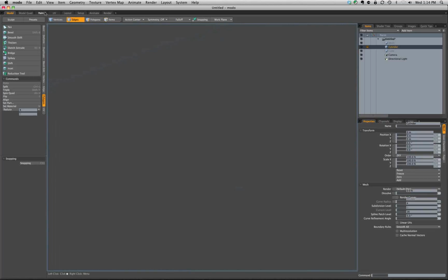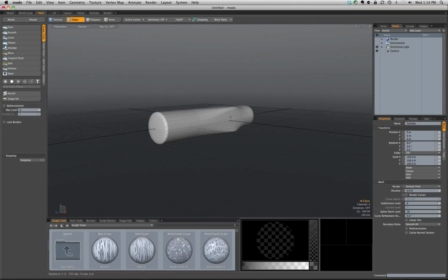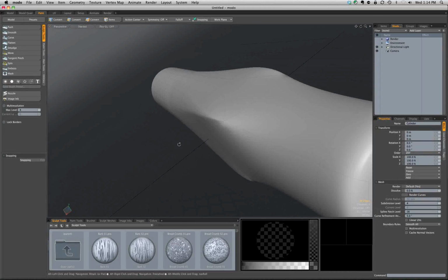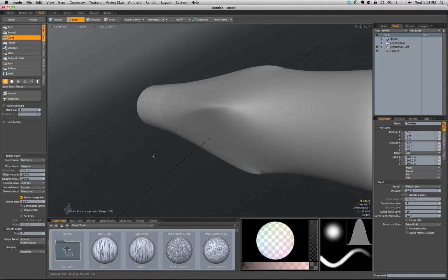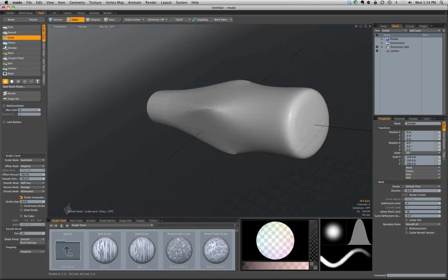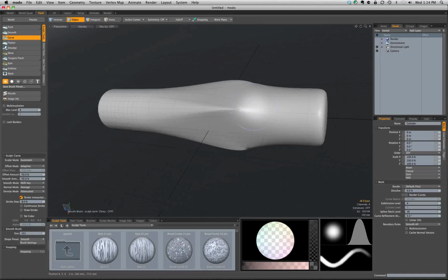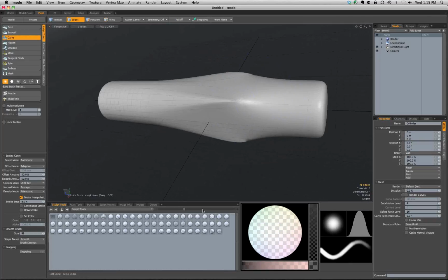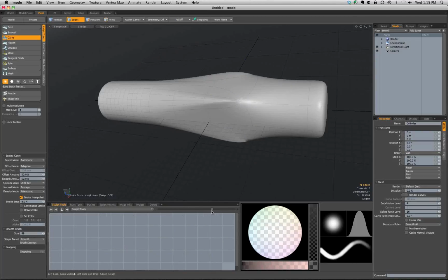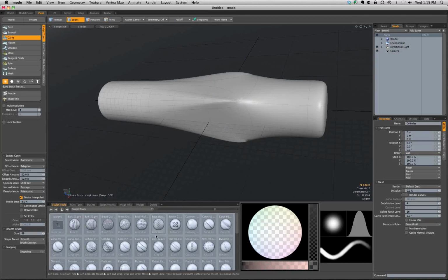So if I go over to the Paint tab and we take a look at our object and go under the Sculpt Tools, and we can just do something like Carve, notice that the tip also gets automatically selected. That's something new for 501 because it is all about workflow. So with the right mouse, I can increase that, and if you take a look down here under your Sculpt Tools, you've got a number of different little presets now, which is always really handy. It's great for creating rocks and grounds and bricks and all kinds of things.